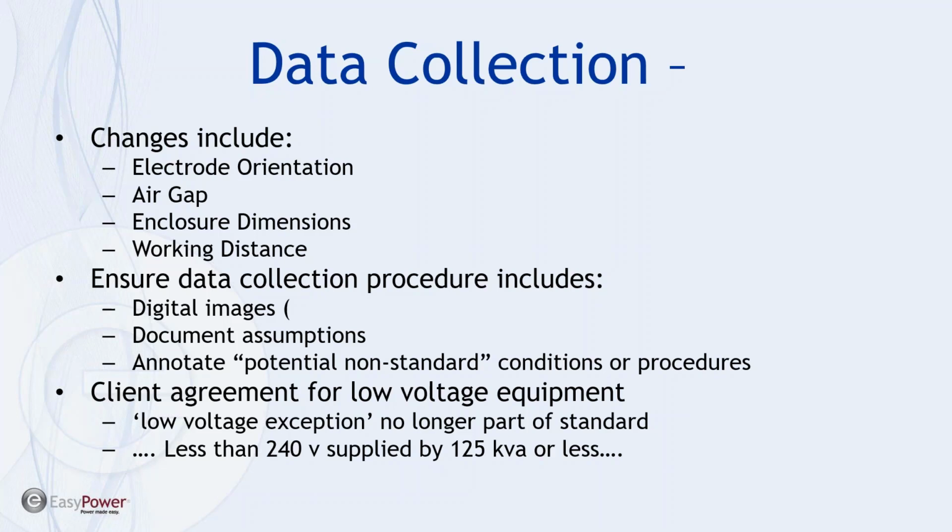The bottom line here is the recommendation is to use standard values that are built into the tool unless you have a borderline bus that's maybe just a little bit too high in incident energy, and you want to go back and see how using the presumed non-standard measurements could have an effect.